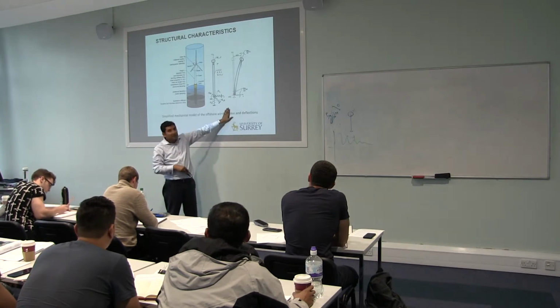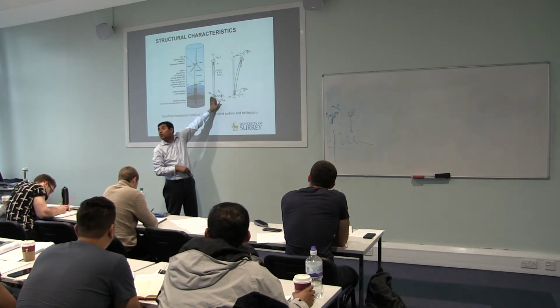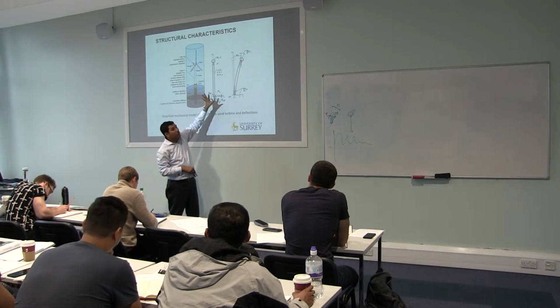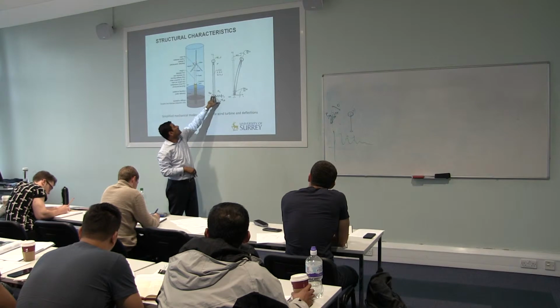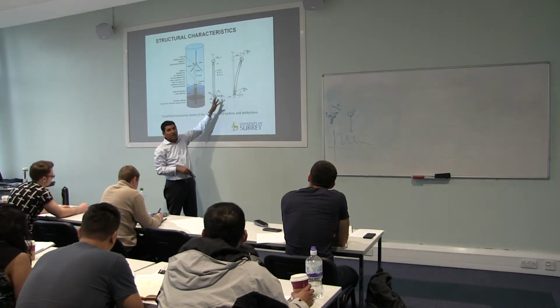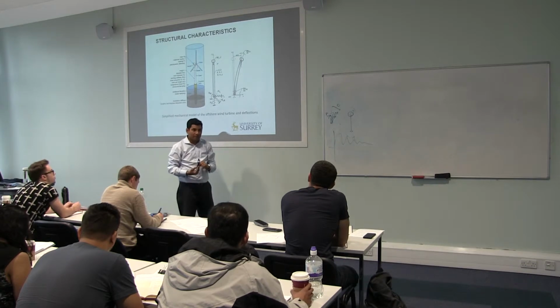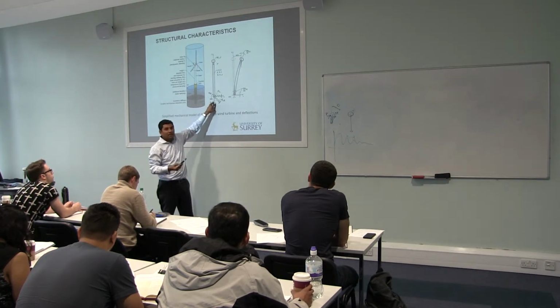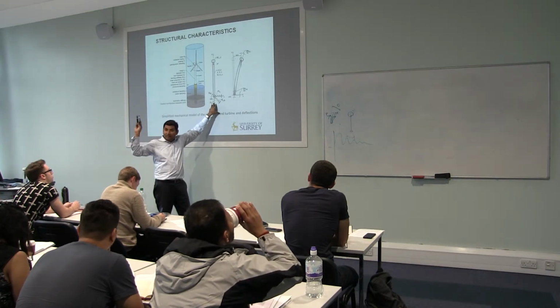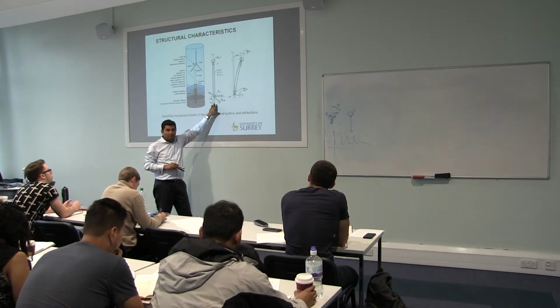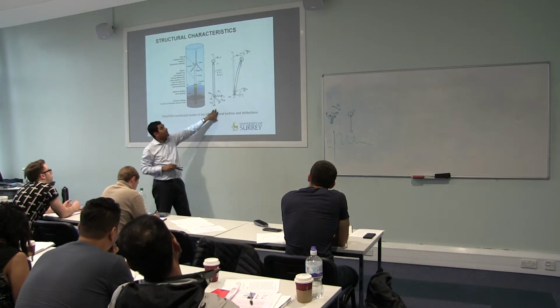Natural frequency is the frequency of the whole structure on its own. Depending on the foundation stiffness, meaning the pile diameter, the soil, the tower length, tower diameter, wall thickness, and top mass, you get one frequency. If you change some components, you will change the frequency again. But the target is what you should aim for.